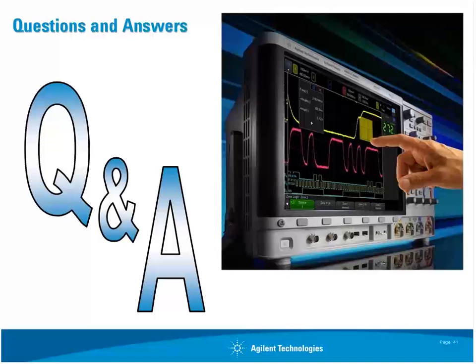But if you wanted to, for some reason, I don't know why, slow down your scope's update rate, if you put in a trigger hold-off of 1 millisecond, then the scope would trigger on an event, then it would disarm triggering for 1 millisecond before it rearmed, in which case the maximum rearm rate would be 1 millisecond or 1,000 waveforms per second.